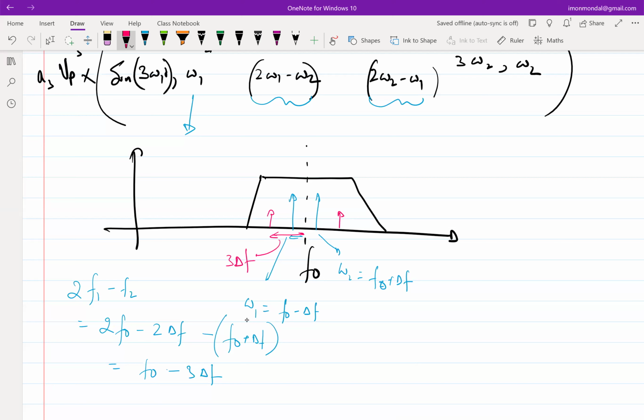You applied a pristine sinusoid at f1 and f2, but you are getting tones very close by, and this can be misconstrued as another signal that is coming in, right? So there is no signal that is there, but because of the distortion, you might be tempted to think that there is another signal that is coming in. So that clearly is not a good thing, right?